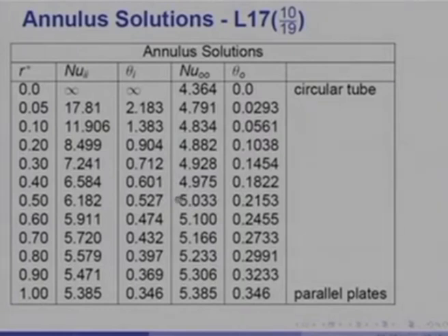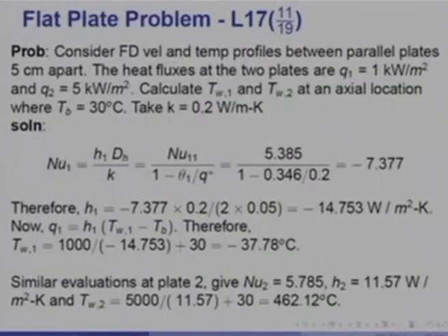Usually Nusselt numbers are not readily available for annulus, but with this method you can now evaluate them for any situation, for any Q wall i, any Q wall o that may be prescribed, and you can readily recover the solutions for the entire family of annulus solutions.